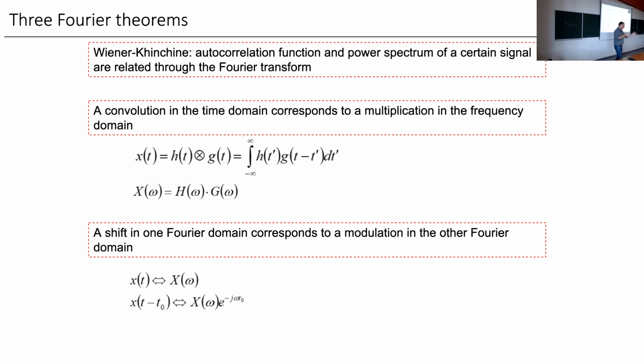You basically take a signal and multiply it with a shifted copy of itself, and you see how big the overlap is between the signal and its shifted version. If you have a signal that varies very slowly in time, then if you move it a little bit, it would still be very similar, and the autocorrelation would be high. If it is fluctuating very hard, even small shifts would change it.